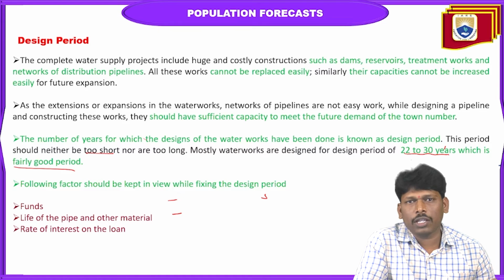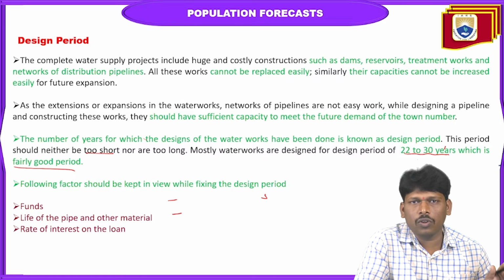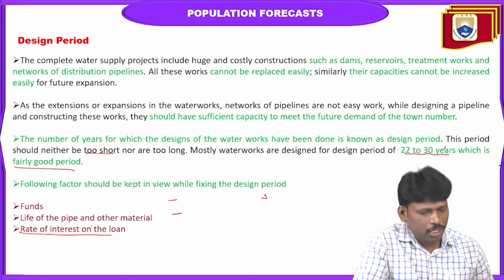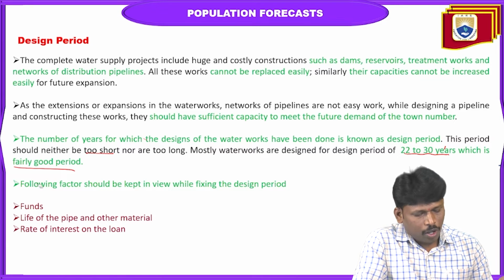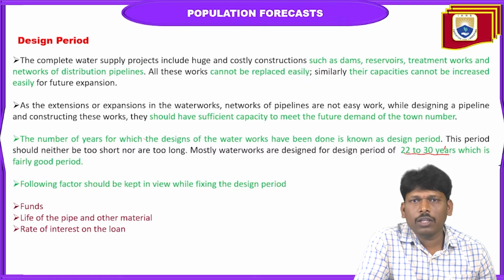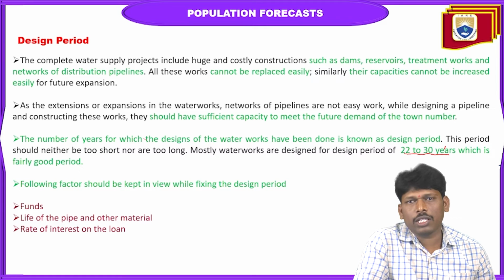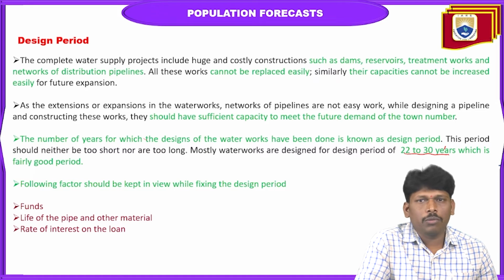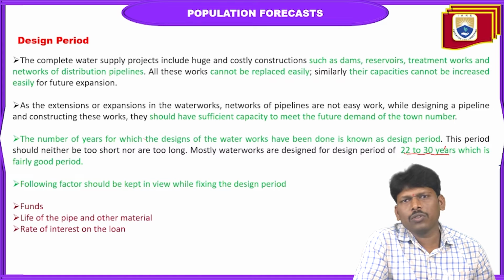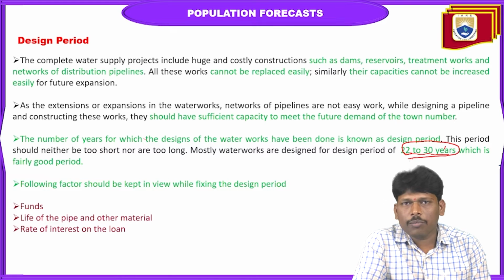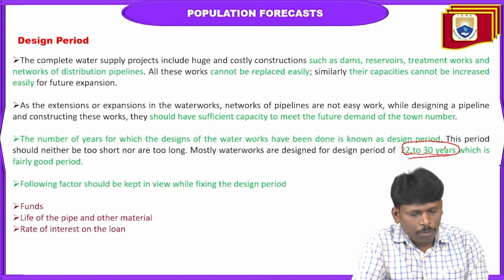So whatever design period we fix, it should not be too short, and at the same time it should not be too long. As I told, the rate of interest on the loans will increase if you choose a long design period. If it is long, the element sizes and everything vary compared to the shorter one. So the material requirement is also more in longer-design structures, and the cost of construction gets increased. Similarly, if you get some loans, the interest increases. So we should keep in mind that for any water-related works, the design period must be 22 to 30 years only. This we need to keep in mind.